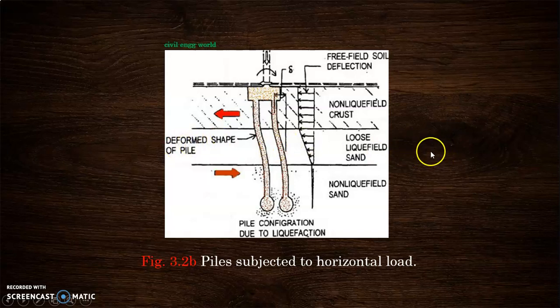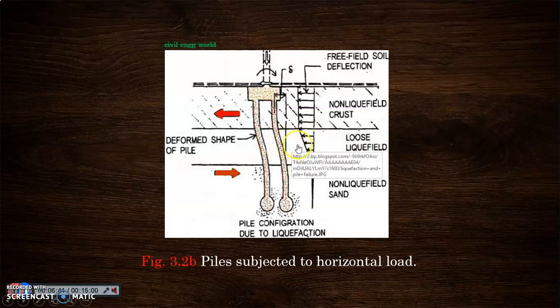So this layer is no good for any load bearing, and these horizontal loads coming from the top because of earthquake, this middle part of the soil layer will be giving no help to the resistance provided by the piles. Hence, the pile in the middle region could be breaking or could be bending.